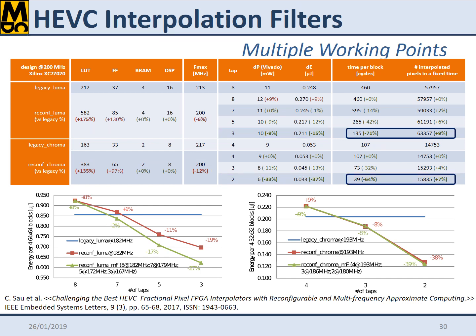Going back to the tables, using a lower number of taps can guarantee a better latency or, equivalently, a higher number of interpolated pixels per execution. This consideration can be exploited tuning the frequency at runtime. The green curves in the graphs are obtained decreasing the operating frequency, keeping constant the throughput. This positively affects energy consumption, as clearly visible in the Luma case, which is on the left-hand side.